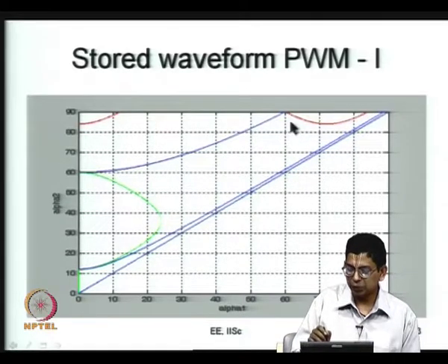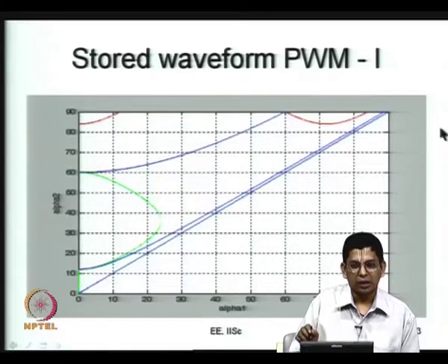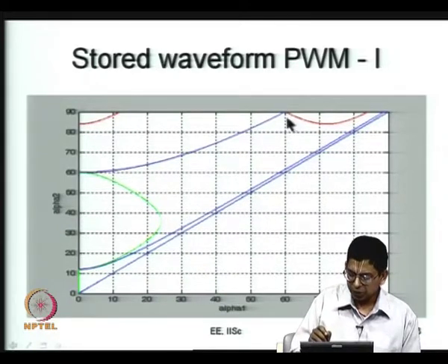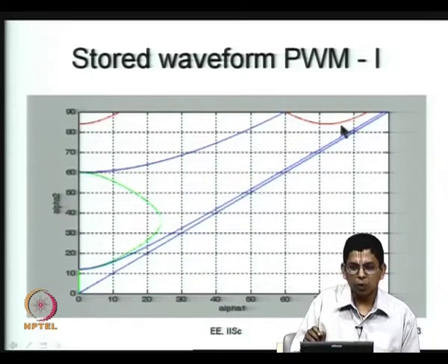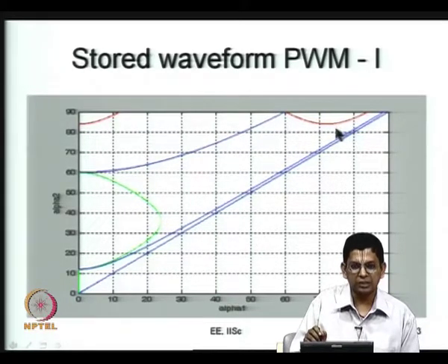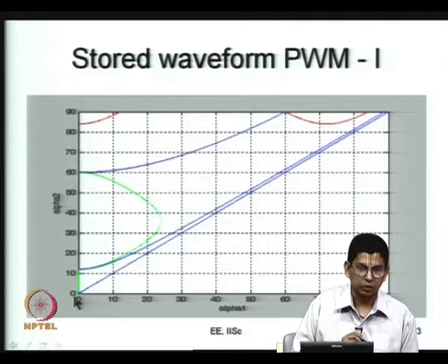Similarly, with the other curve, if you had chosen this one, fifth harmonic would not be there between 0 to 0.8, but between 0.8 and 1 there will be a certain amount of fifth harmonic certainly there now. It is also possible for you to start with this curve and follow it up to some point and jump back from there to here with the same V1, say at V1 is equal to 0.6 or 0.7, some intermediate point, you can jump over here and follow this curve and move over there now, that is also possible.